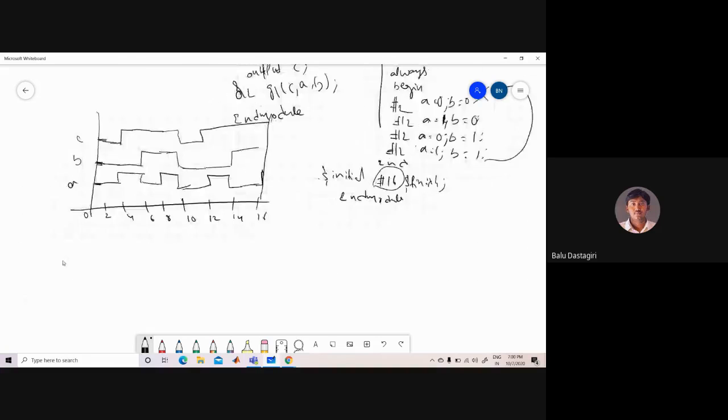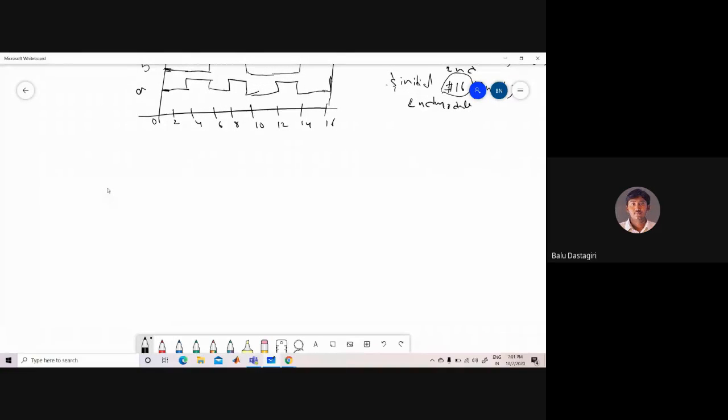For example, let me take a simple AOI gate here. It is AND of A, B and AND of C, D, followed by the OR gate, then followed by the invert gate. That is the output stage. Let us see how you can define the test cases for this. The gates are G1, G2, G3, G4.